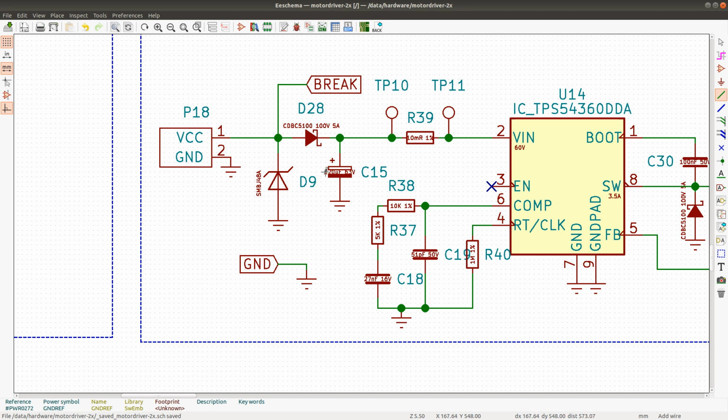So what I could do here is I can keep this capacitor. Originally I thought that I would actually move this behind this current sense resistor, but I can keep this capacitor where it is. The main purpose of this capacitor is to provide any extra current when the supply voltage may drop way below the actual nominal voltage on the supply.